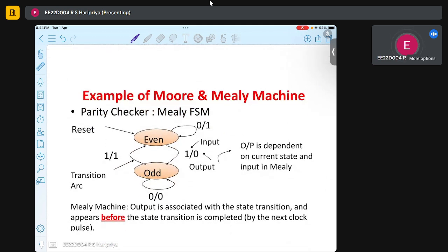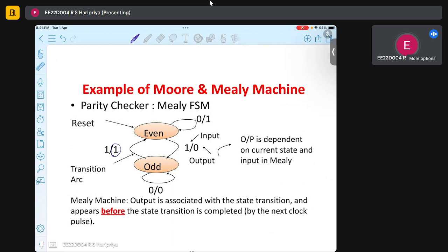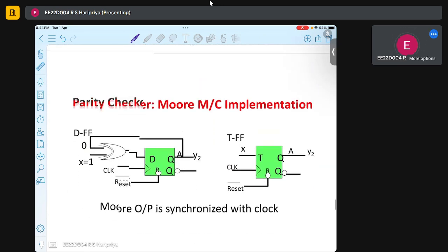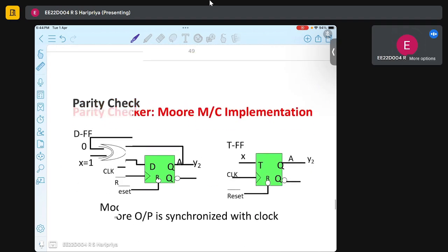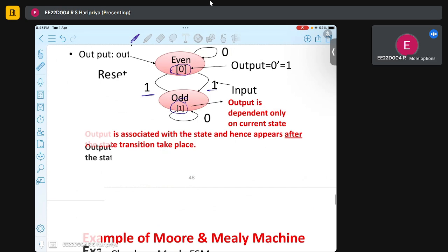First, taking a Mealy example by example, we can define the output for every transition. For every state we have an output, but here the output for Mealy depends on the input. So based on the transition, with the input, it is transitioning from this state, we have a particular output. If we have a circuit, for Moore, this is the output for the state, and for transitions, based on inputs, the transition happens, but the output only depends on the state, not on the input.